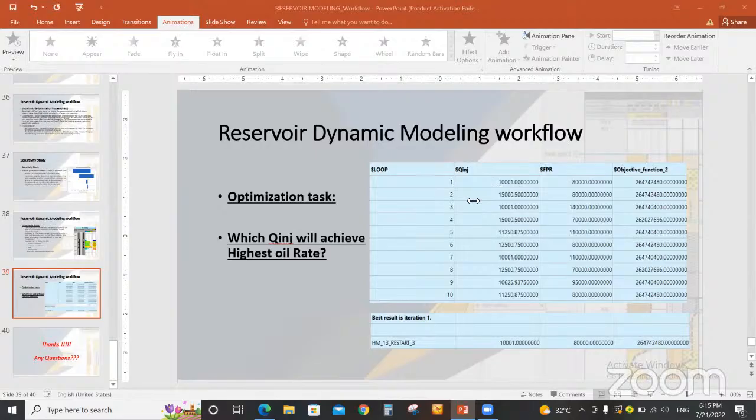Why use normalized capillary pressure or relative permeability instead of using each curve? Actually, for capillary pressure and relative permeability, we have many blocks, and each block has its own relative permeability and its own capillary pressure. We want to have one relative permeability curve and one capillary pressure curve for the whole reservoir model.